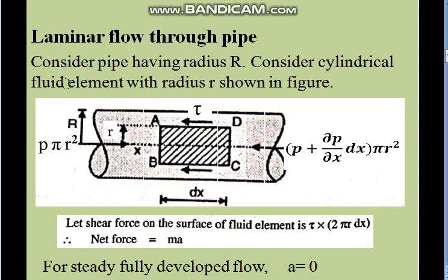Now in this horizontal pipe, as we are considering here along horizontal as x direction, and I will write Newton's second law, which is about the forces. In this x direction there is no gravitational force, so basically there will be only two forces. One is pressure force and second one is the shear force.